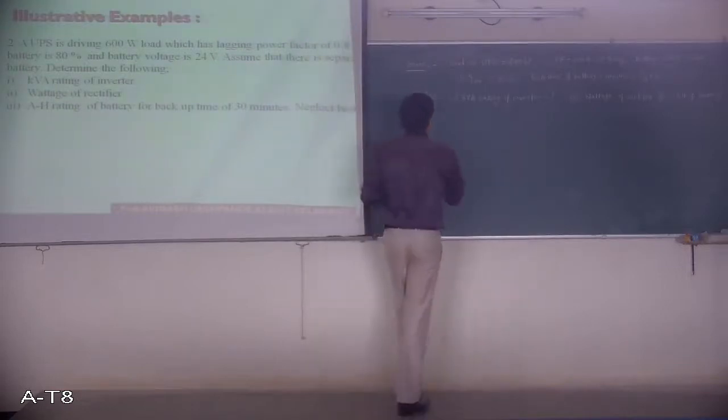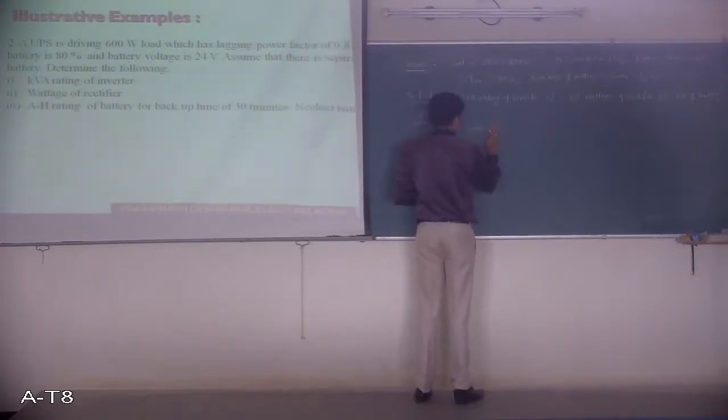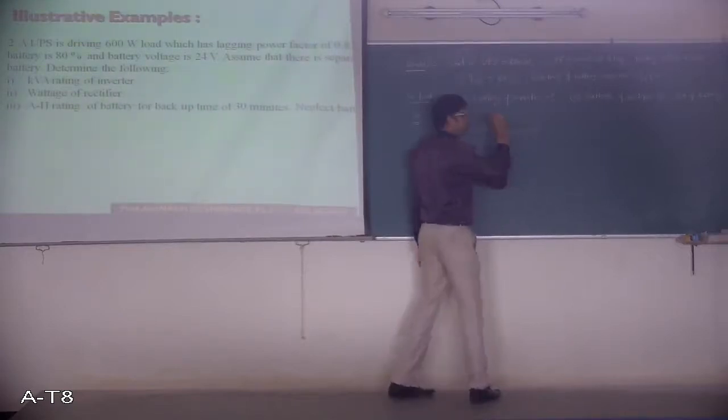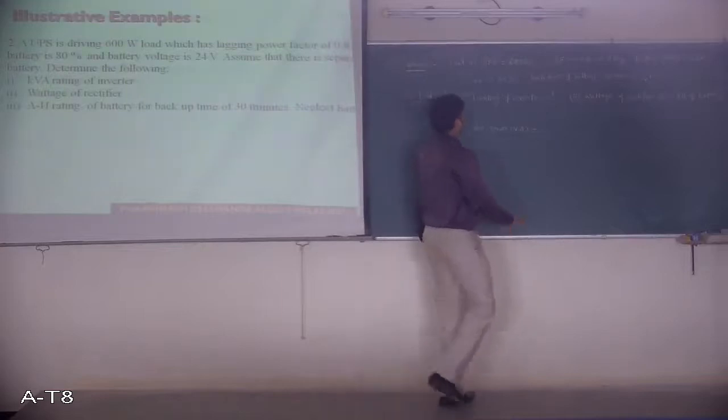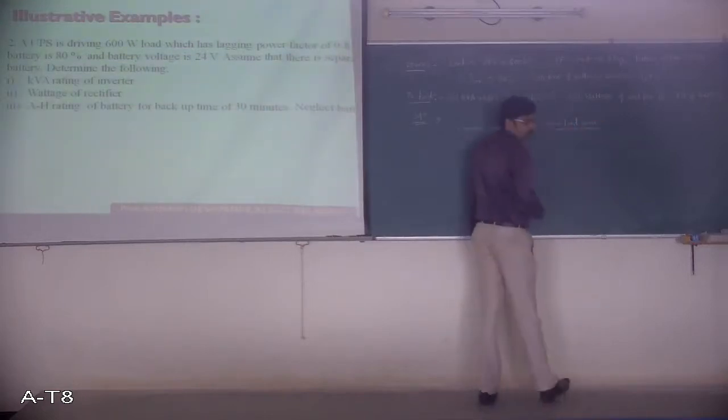Now, inverter KVA rating. I will write inverter power, which will be in terms of VA, is equal to active load power divided by power factor of load.